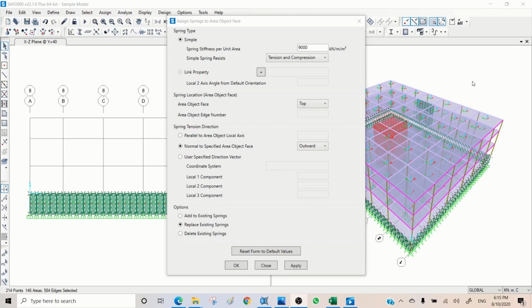And if you have load in the opposite direction, a negative x-axis, what will happen? This side is fully under compression. This side you have no resistance because there is no tension on soil. That means always you have one side fully under resistance. So how can we simulate this? Because tension and compression would work in both sides.